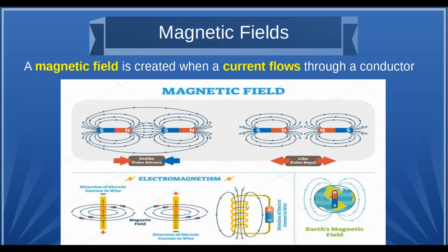Now, when we take that wire and we wind it into a coil, the magnetic lines of force tend to concentrate in that common area between them. Okay, so this is how we build what we call an inductor. Now, a wire by itself has some inductance, but basically you need many turns to get a lot of inductance. And to get even more, you put a material in the core that has what we call permeability, and it can concentrate the magnetic lines of force. In other words, it acts like a magnetic conductor. So it's things like iron or the ferrites and things like that, which have very low magnetic resistance.